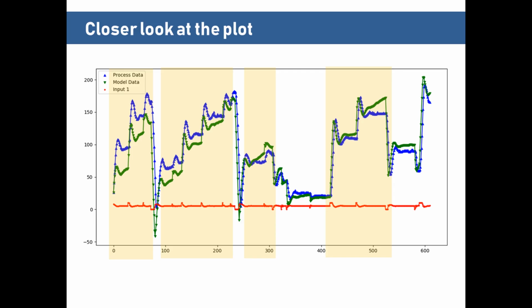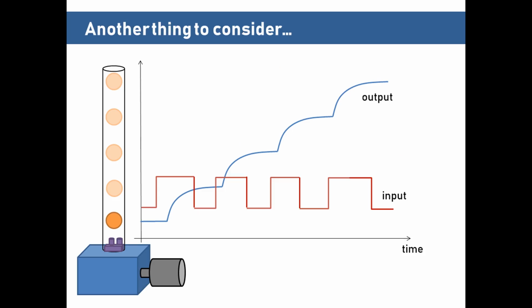And this property of our air pump system is something that we need to consider in order to refine our model further. So in our system, say we crank the input up to 100% for a short period of time, and we do this several times. Each time we do this, our output gets higher and higher, even though our input change each time has been the same.